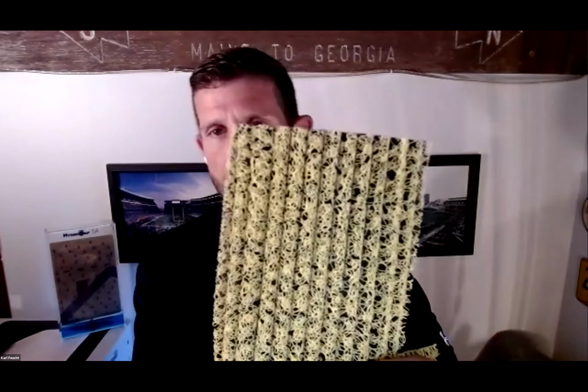But in a commercial application, a lot of times that WRB is exposed longer. Some of our products, like this one here, our rainscreen product, has a 30-day UV resistance. (I didn't hold my samples up when I was doing the presentation, I should have.) So you wouldn't want to put this product up when you know that siding's not going to be on for 90 days or 6 months. That's going to create a problem. So that's really the limitation when it comes to the commercial side of things. I hope that makes sense.